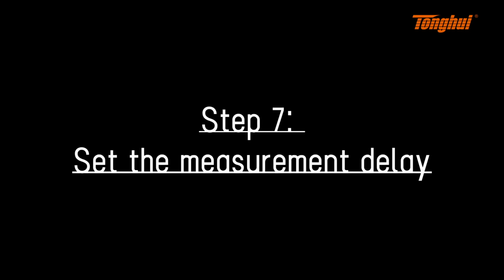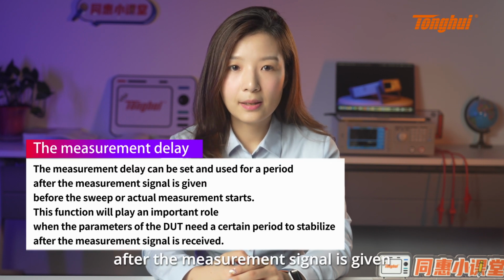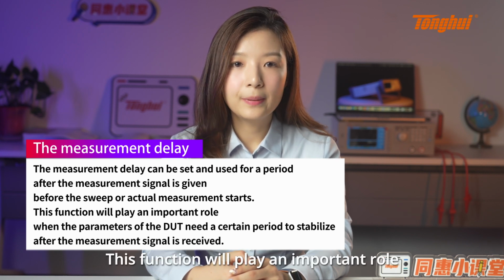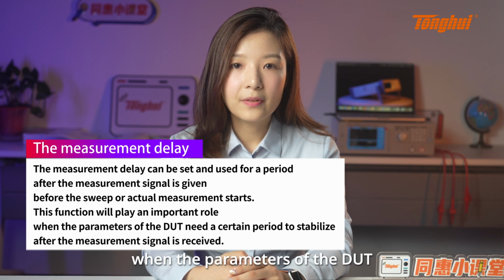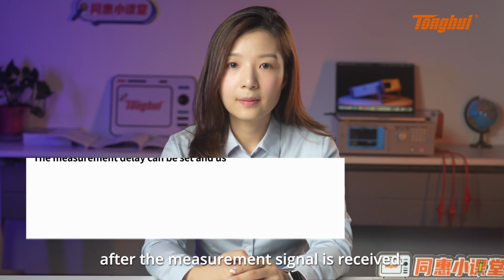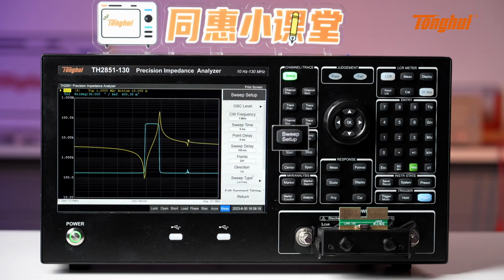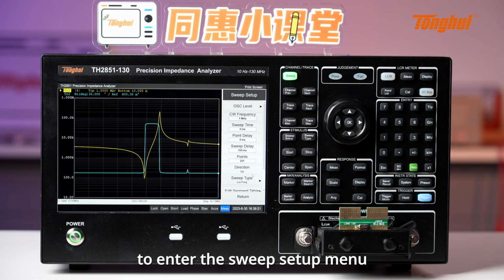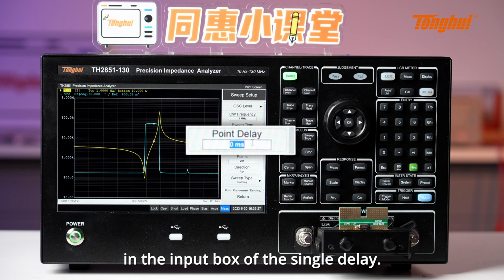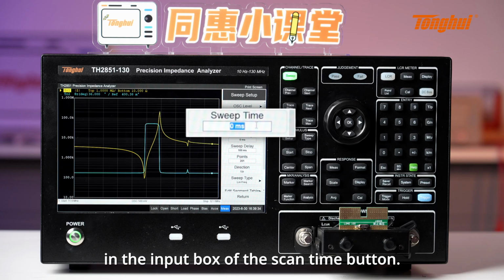Step 7. Set the Measurement Delay. The measurement delay can be set and used for the period after the measurement signal is given before the sweep or actual measurement starts. This function plays an important role when the parameters of the DUT need a certain period to stabilize after the measurement signal is received. We modify the single point delay and scan time through the following steps. Press Sweep Setup on the front panel to enter the Sweep Setup menu and enter the single point delay value to be modified in the input box of the single delay. Enter the scan time value to be modified in the input box of the scanning time button.